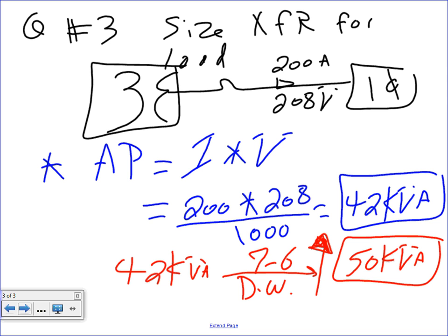It says in the book it has to be 10% greater than the load. The transformer must have a kVA capacity 10% greater than required by the load. That's for, later on we'll say, continuous load. Leave this until the end. I didn't say anything about continuous load. If it's continuous load, usually I add 1.25, pump it up a little. You have a good point.